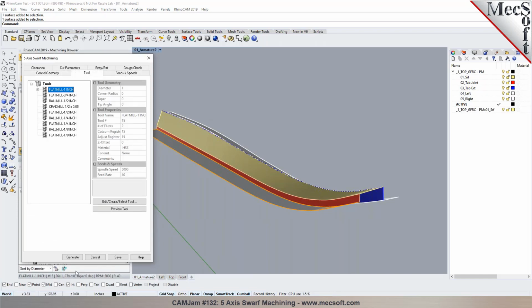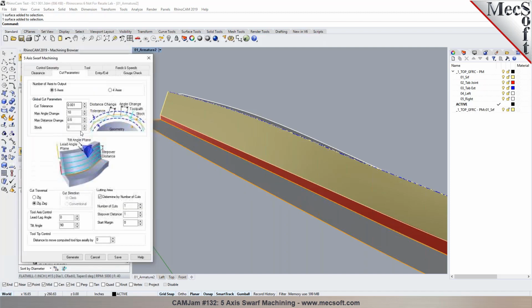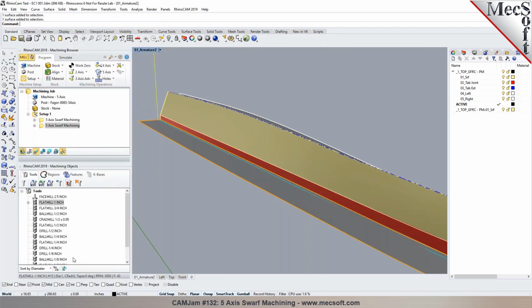And if you wanted to cut slightly below on this particular one, if this is just like a support and you wanted to cut past it, you can always use what is called a distance to compute, like a tooltip clearance. I could say maybe -1/4 inch. So it's actually going to push the tool down by that amount if you just pick the floor curve.